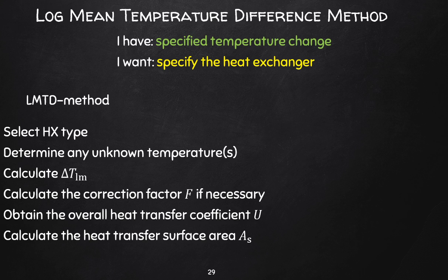Alright, the next thing to do is to determine the log mean temperature difference, and then for non-latent heat applications, where you don't have a phase change, a correlation factor is also determined using temperature ratios. We'll get into that just now, as well as the overall heat transfer coefficient. And lastly, the area of heat transfer is determined.